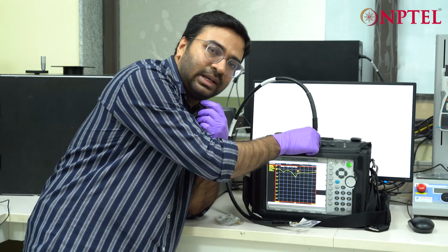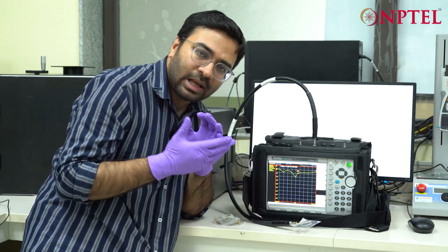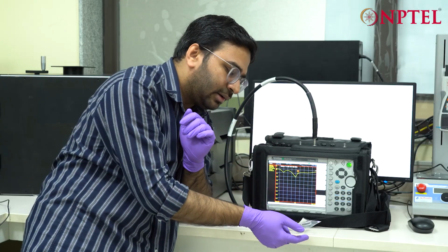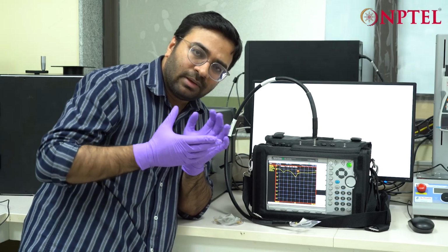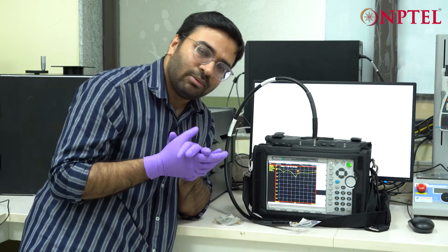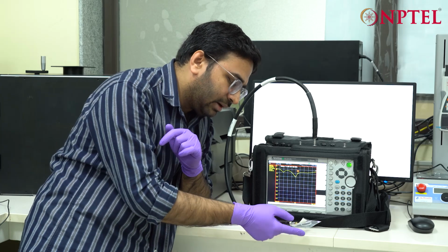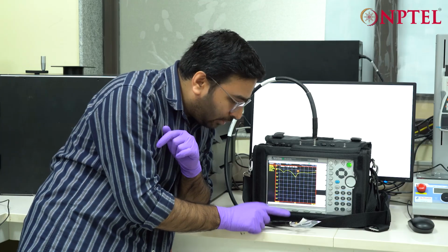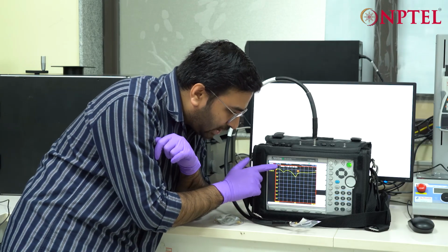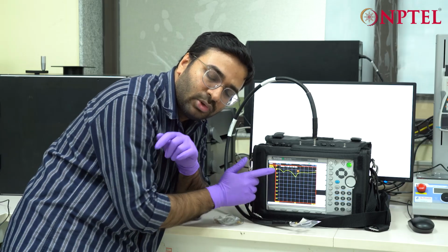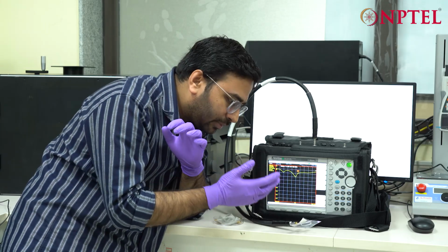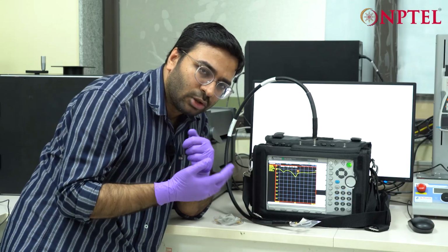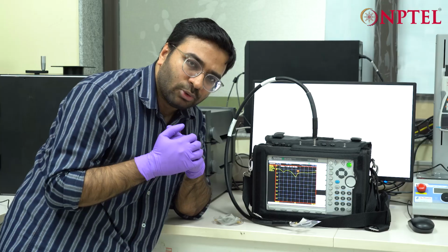One port we are currently using, and just to give you an example, what we have done is we have connected this probe with one of our flexible antennas. So we develop flexible antennas also. We have connected this with a flexible antenna that is connected over here using an SMA connector. And now you can see that you get the S11 parameter in this VNA. So you can measure the return loss of the antenna using this VNA. You can measure other S parameters also. This is just for demonstration purposes.